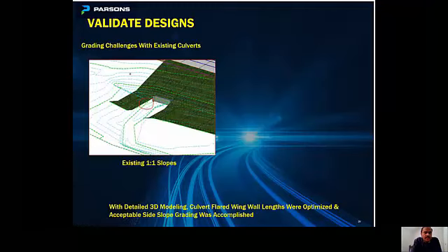So in this slide, you can see in one of the locations, the original plan was to salvage the existing culvert and not disturb that culvert. And then when we were developing the detailed grading around this area, there was a proposed driveway, and we were checking the slopes, and we noticed that the existing slopes were pretty steep, one-to-one, and they were not complying with the design criteria for this project. And later on, we brought this to the attention of the drainage engineer and other contractors.